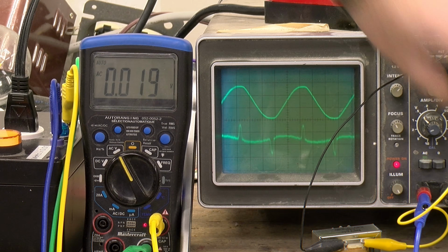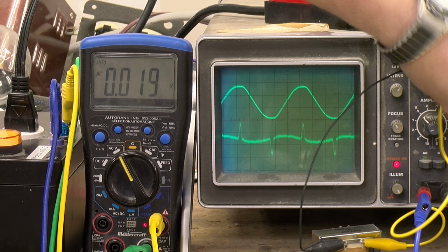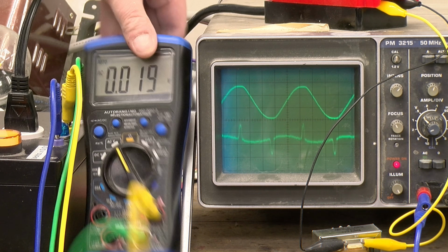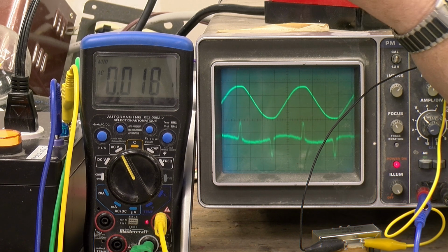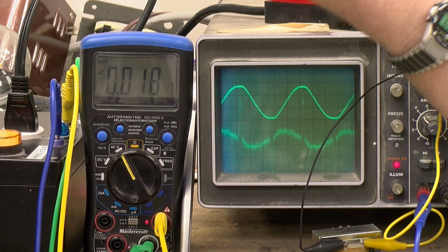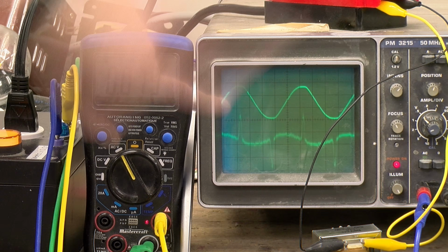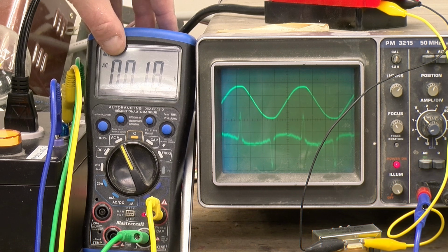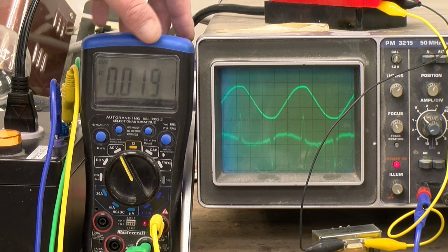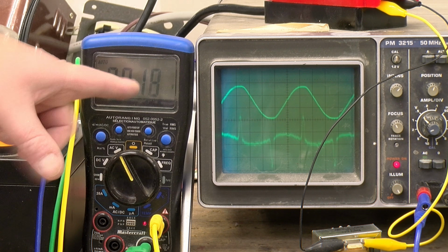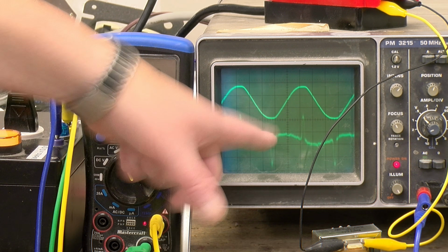The laptop is not turned on, and what you can see on the current is a very peaky current, just like we've seen for some of the more lousy light bulbs. The current itself is only 20 milliamps, and that's because the power supply is operating in some sort of a low power standby mode. Now, I'm going to go turn on the laptop, and what we'll do is see what happens to the current and the waveform over here.